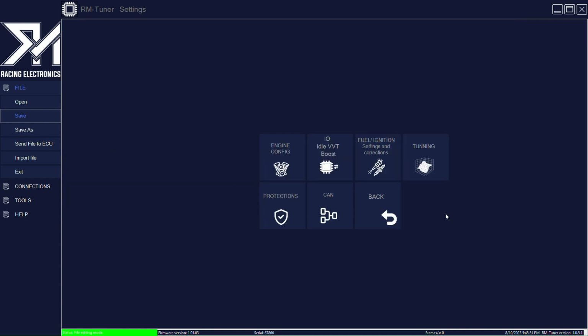So another thing that we have now is on the CAN settings. You can activate the bit fields, and you can configure something like a bit from one of the bytes to change something like direct control, which will be like a 1 or a 0. The inverted, which is the opposite, toggle on rising or toggle on falling, which is basically a push button.